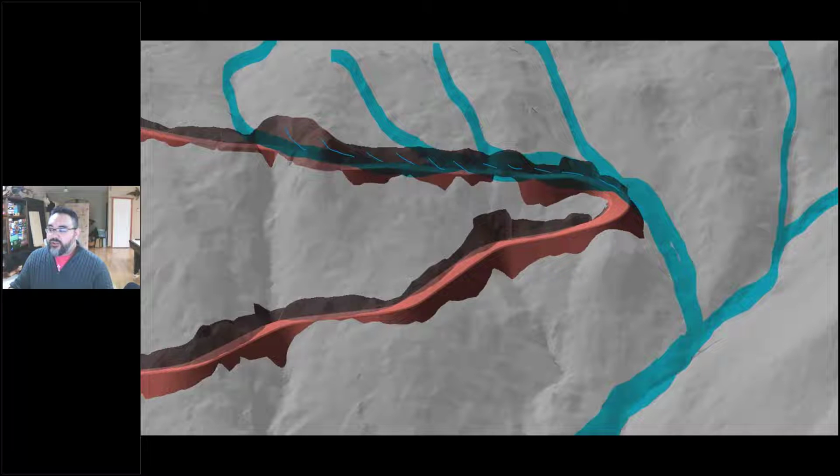And so not only have we changed that accumulation and concentration of flow and redirected it, we've redirected it into a drainage path that has not seen those flows before. So even if we just increased the flow in that channel, it would be bad. But now we've increased it by putting different channels. So it's not just the impact on that channel, it's the impact on the hillside that's below our road, where now there's no water flowing.